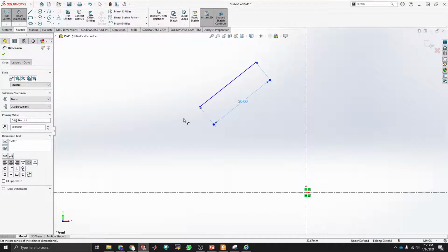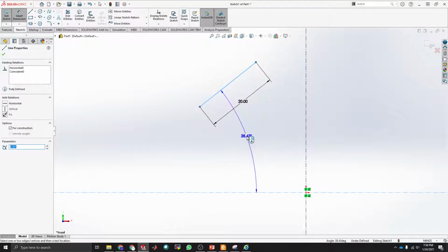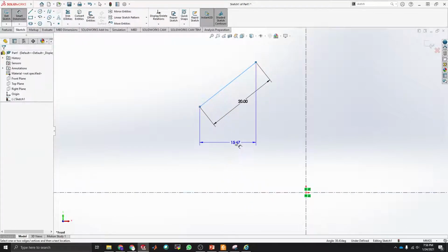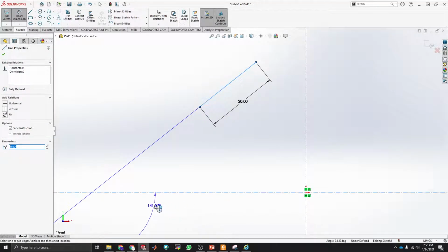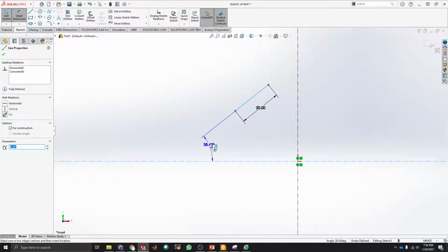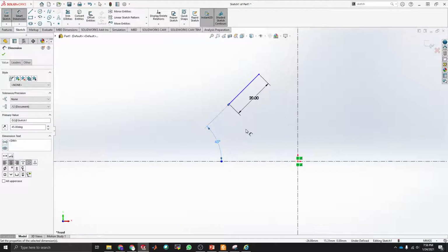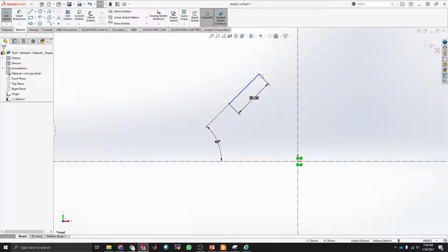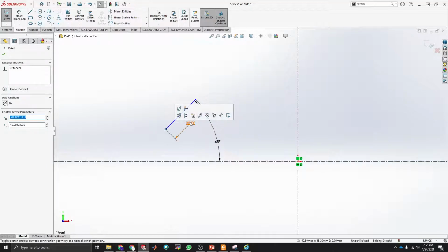And then I can also define maybe relative angles between 2 lines. So I can select first one line and then this other line, and I can define either this big angle or this inner angle. Let's suppose that this one is 45 degrees. Now as you see, if I move one point, the other one will also move, preserving those 20 millimeters and preserving these 45 degrees.